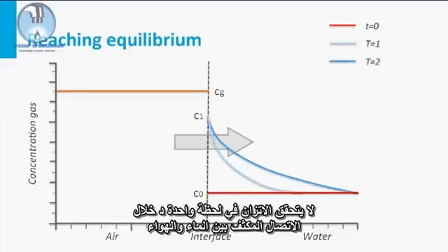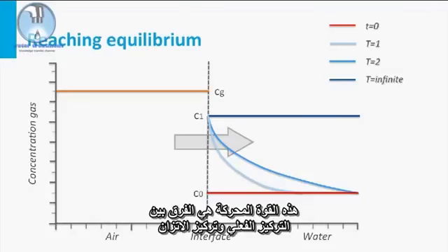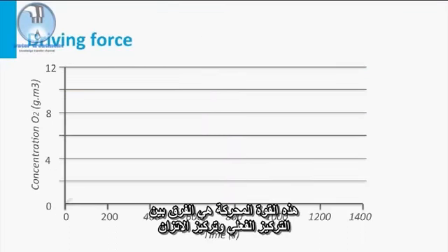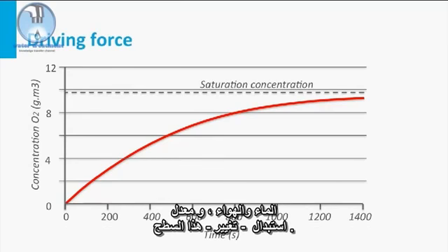Equilibrium is not achieved at once during intensive contact between water and air. Rather, the gas exchange takes place at a rate that is linear to the driving force. This driving force is the difference between the actual concentration and the equilibrium concentration. The gas transfer coefficient depends on the magnitude of the contact surface area between water and air, and the rate at which this surface is replaced.